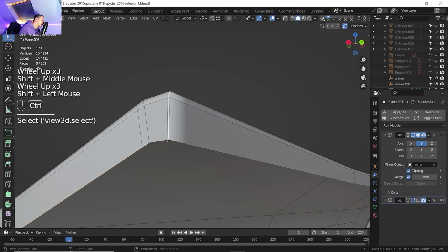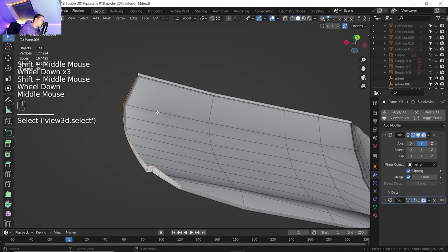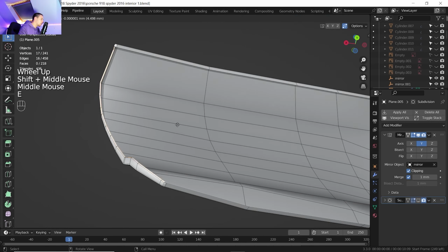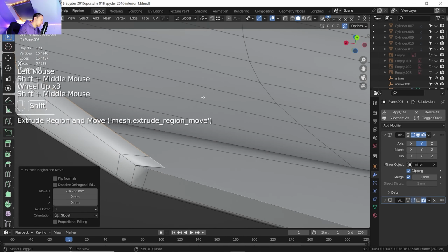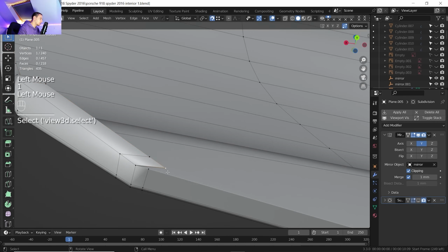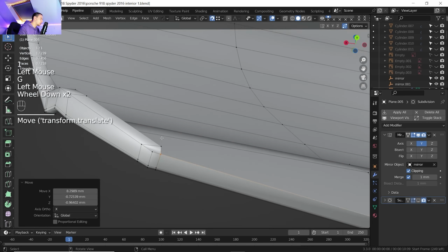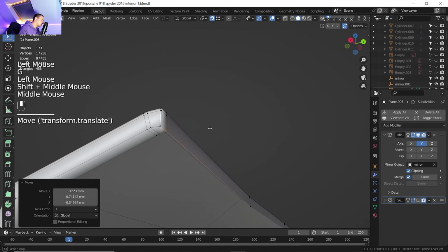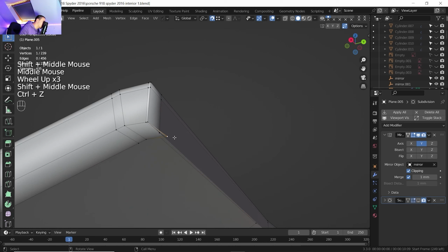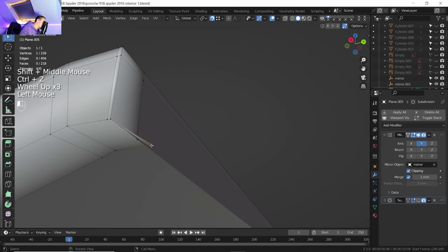So I'm going to select also this small edge around here, and first off I'm going to extrude and go on the x-axis. But what's happening? I will enable snapping, and I'm going to merge this point around here, and this point is going to be around this part. One second, I've merged them or something.